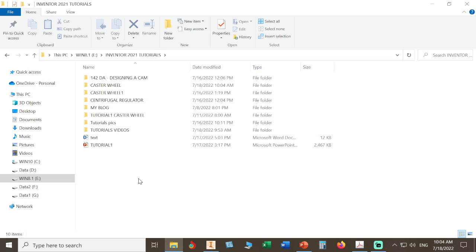The main problem will be faced with standard parts. The location of the library of standard parts here may differ from another PC. So what to do? In order to take all your work, you have to pack and go your work.